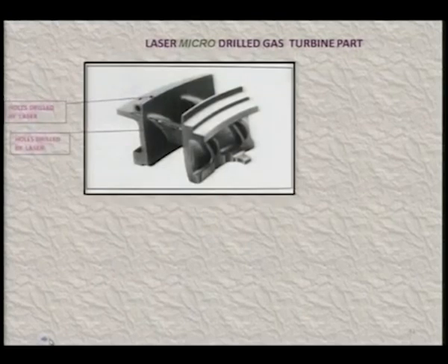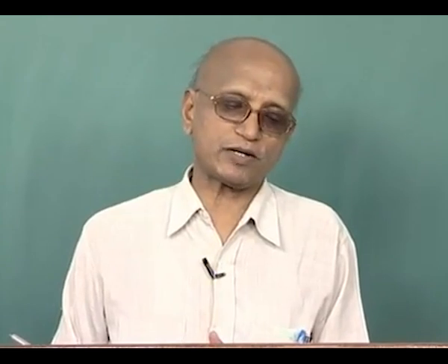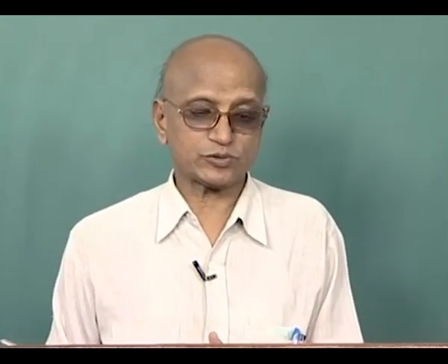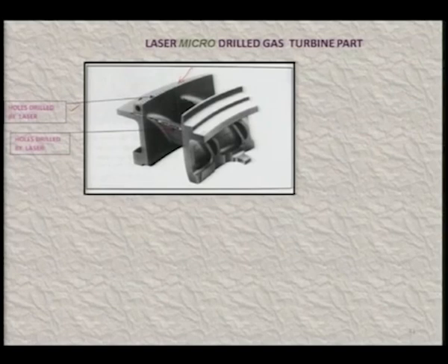Now, this is a very interesting application as long as lasers are concerned. Turbine blades, laser micro drilled gas turbine parts are there. All these turbine blades have thousands of holes, which may be micro, which may be macro, drilled in super alloys which are used for making these turbine blades and other parts of the turbine. You can see here clearly holes drilled by the laser, very fine holes, and these holes have been drilled in super alloy with the help of a laser beam drilling setup.